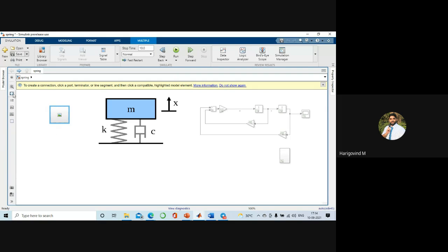In Simulink, everything is solved as differential equations. That is one of the disadvantages of Simulink, which we are going to overcome using either Simscape or Stateflow or Powertrain, etc., the extra tools available with MATLAB. So whenever we need to solve or model anything in Simulink, we mostly prefer differential equations for that physical representation.